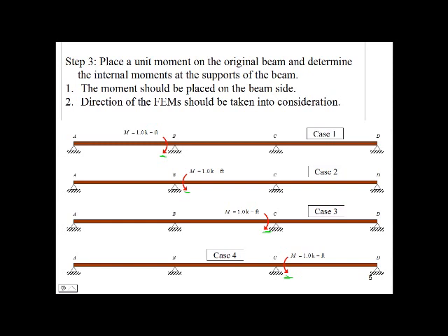Case 1 represents beam 1. Case 2 and Case 3 represent beam 2. And Case 4 represents beam 3. Please pay attention to the direction of the applied moment. The applied moments should be in the same direction as the fixed end moments.